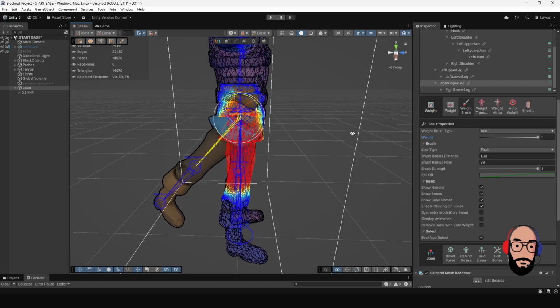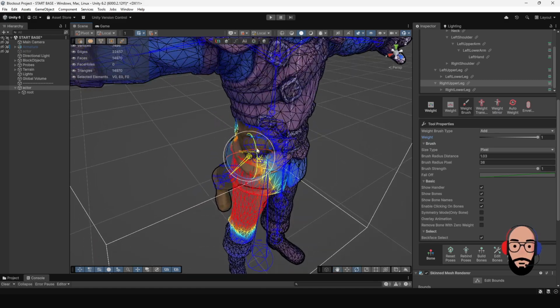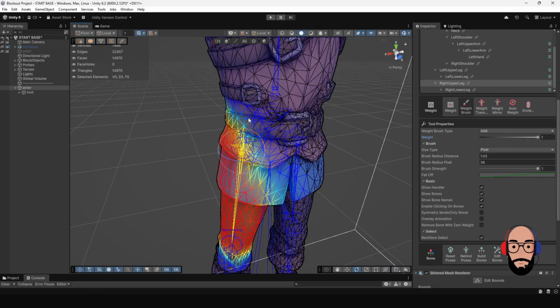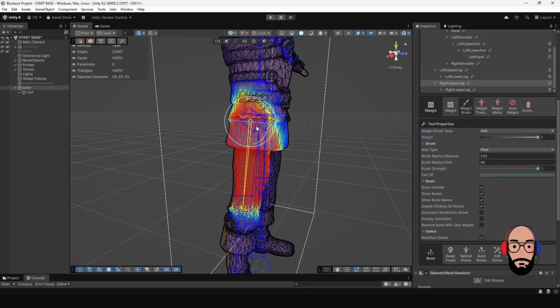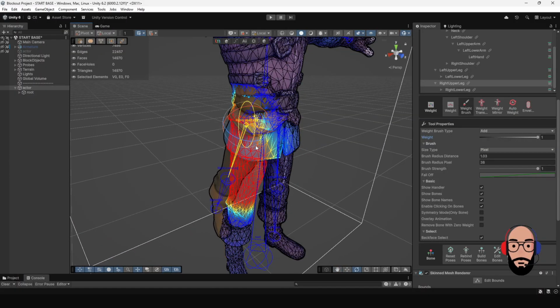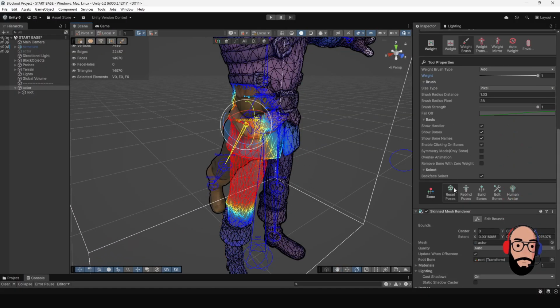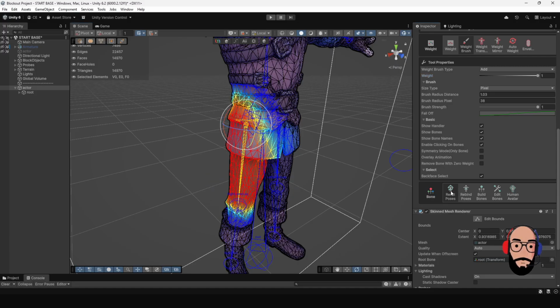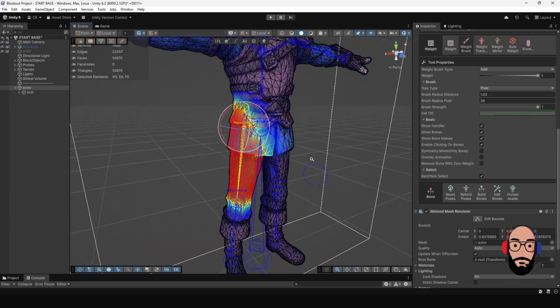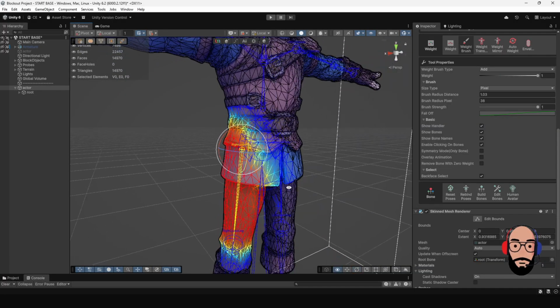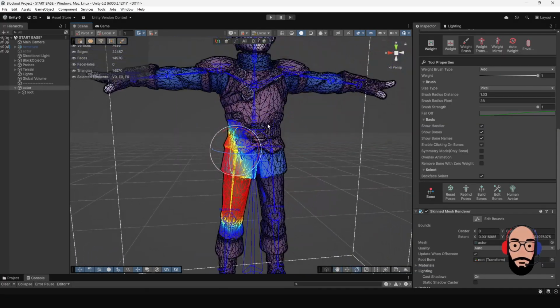So what we can do now is move this leg. Now, in most cases, you would think, well, you can just kind of move the leg and kind of angle it back within that point, and that could work. But a more accurate way to do it actually would be to go down into the bone group and click on Reset Poses. So when we click on Reset Poses, it's going to reset it exactly back to what it needs to be. Perfect.